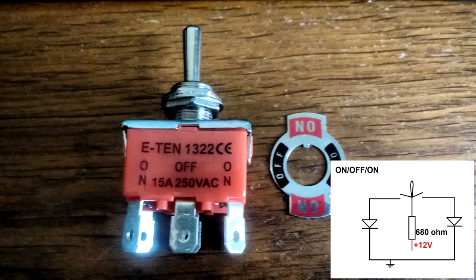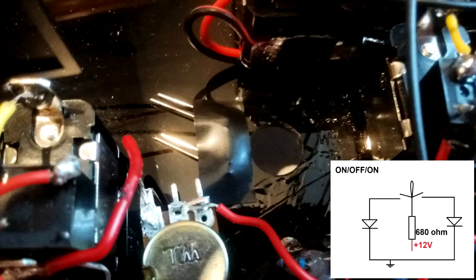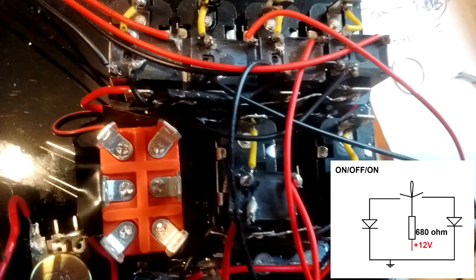I was waiting for this button and I mounted it at the end. I'm going to show you now its installation to respect the chronology. On the plastic plate I had drilled two 3mm holes. I've put two white LEDs with the cathode on the top. I've put some insulating tape because there is a metal part on the switch. Here we have the switch on the hole.